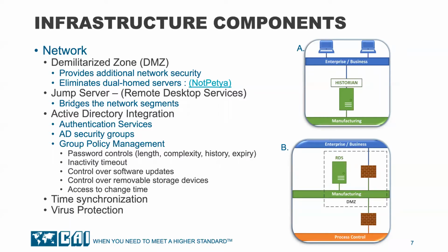Automation vendors often need remote access to level 2 systems to support troubleshooting. The automation software can be installed on the RDS server, and the automation vendor can access it using a corporate VPN. Many supplier remote access solutions seriously compromise security.